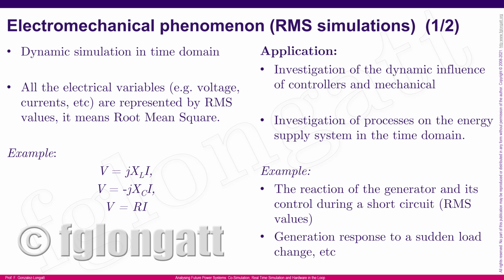On the other hand, we have the electromechanical phenomenon, and we use what we call the RMS simulation. In the RMS simulation, we care about voltages and current, electrical quantities, and those electrical quantities are represented by phasors. To be honest, this is a very good simplification that allows us to solve the problem in a very simple way.